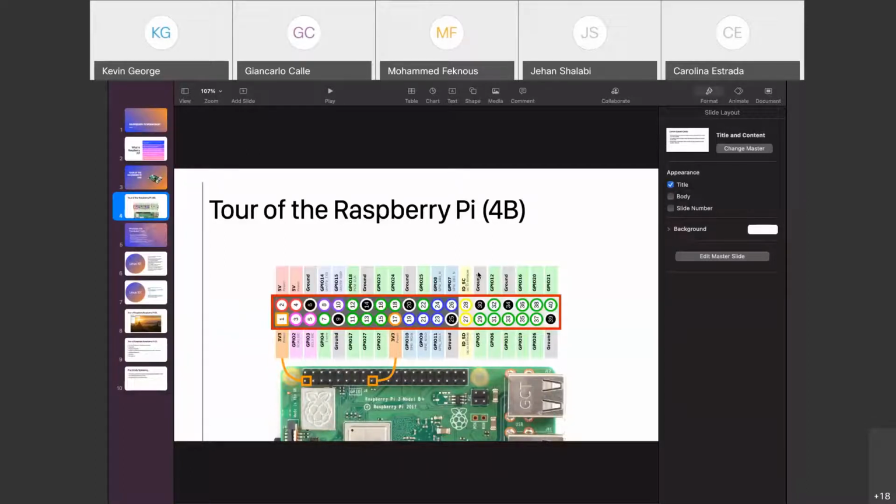In this case, how we're going to wire that up to the breadboard is we're going to have our voltage and our ground. We're going to hook up our 5 volts to one of the voltage rails. We're going to try to use the positive left-hand voltage rail so that it'll be easier for us to visually indicate, and that's going to be our pin 2.